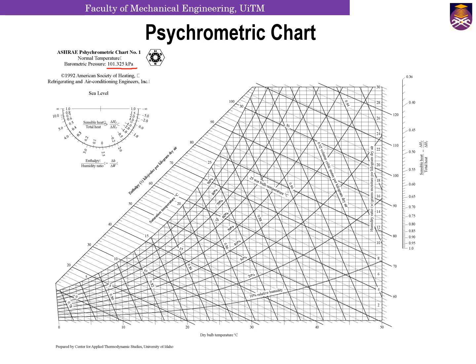For 100 kilopascal, you will have no choice but to use the earlier equations. But if your pressure is at 1 atm or 101.325 kilopascal, then you can freely use the psychrometric chart to solve problems related to air conditioning processes.